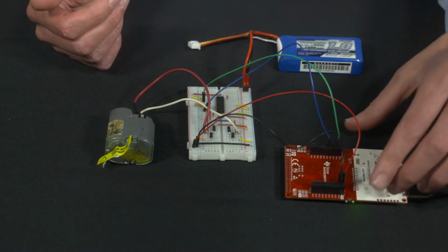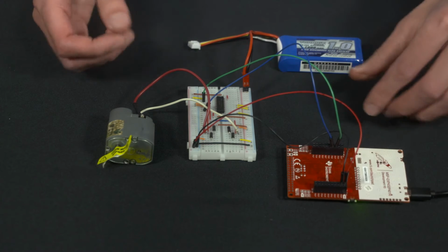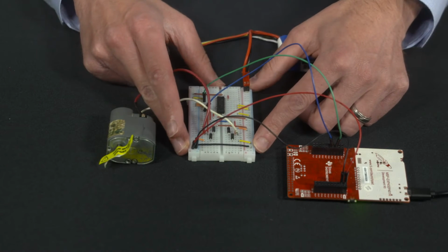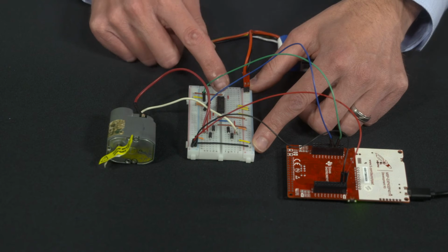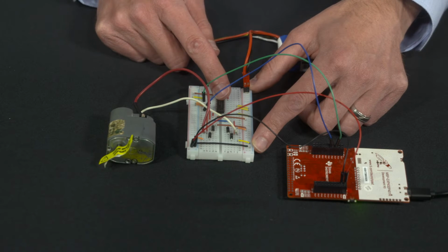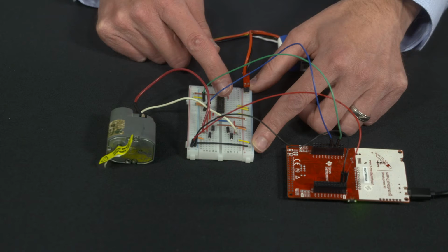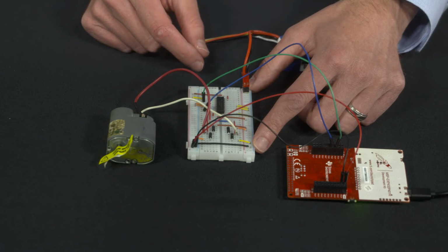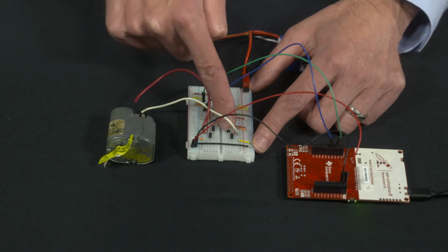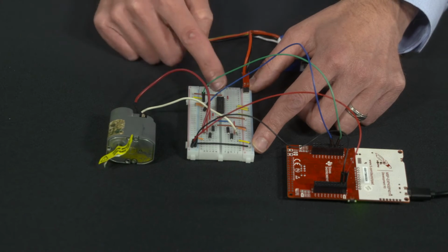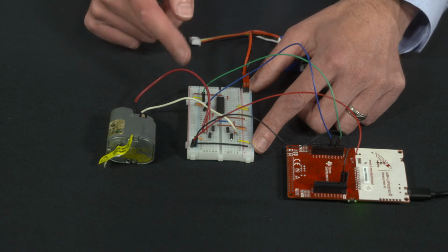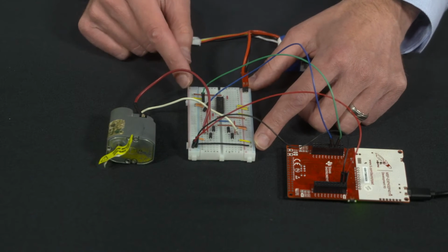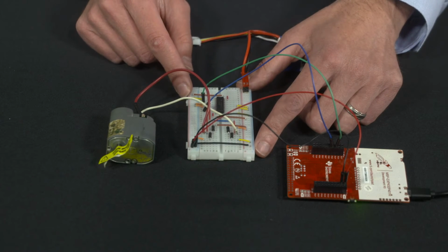So the main components we have here are our Launchpad microcontroller, we have our motor, we have a battery, and we have a breadboard, which is containing our H-bridge integrated circuit right here, and this is the TI L293 H-bridge. And then the only other components on this breadboard are 4 flyback diodes you can see right here. Now the H-bridge has flyback diodes incorporated in it, but we also include flyback diodes just to protect the H-bridge itself. And so you can see these are the main circuit components we have on the board.